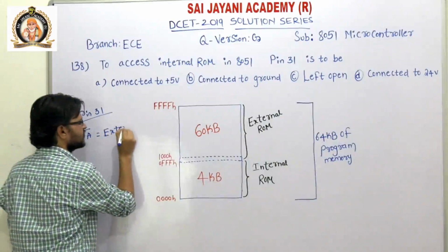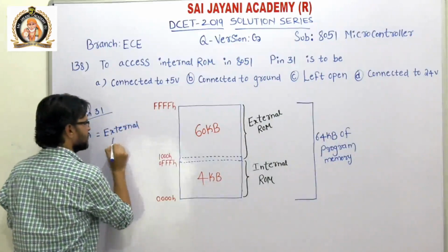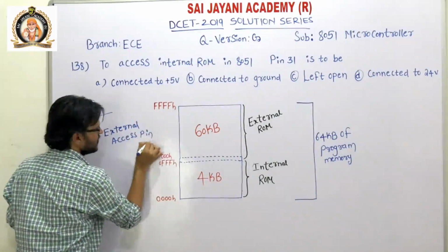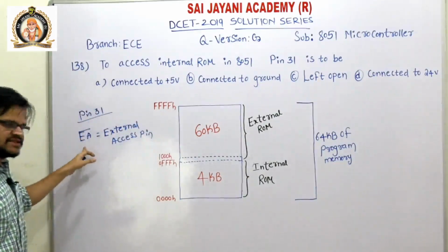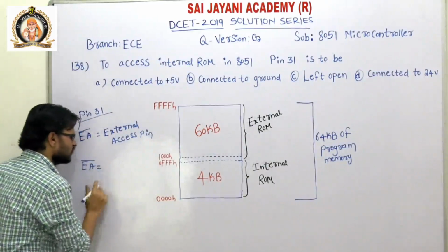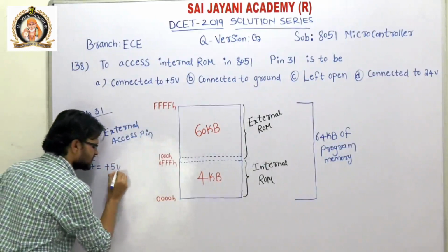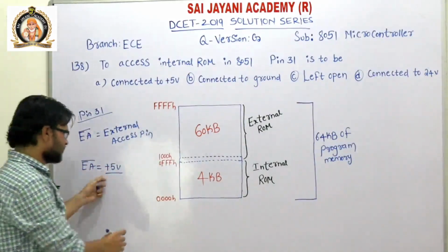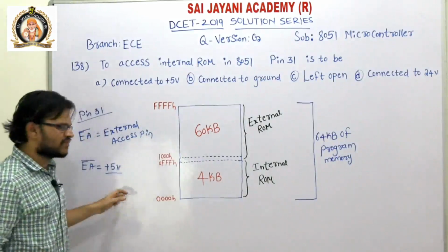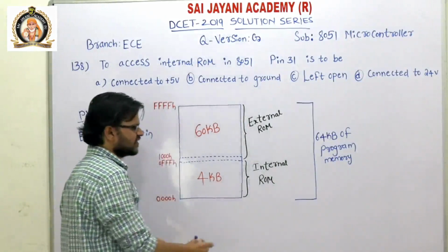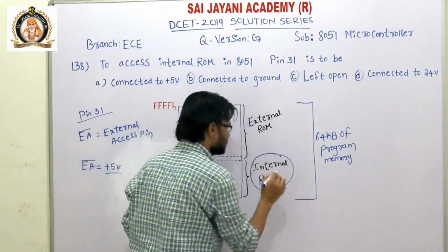When this external access pin is connected to plus 5 volt power supply, then the program or the code is stored in the internal ROM itself.